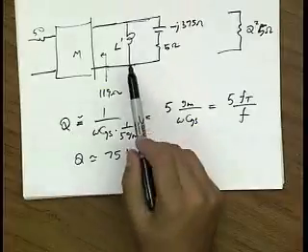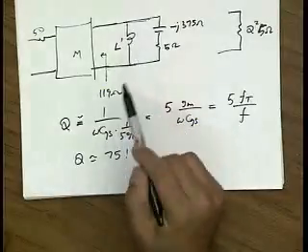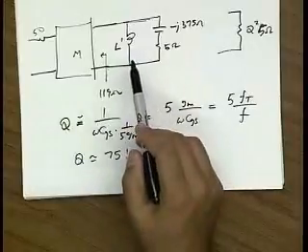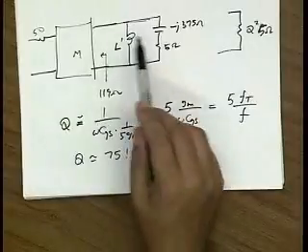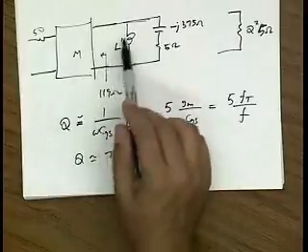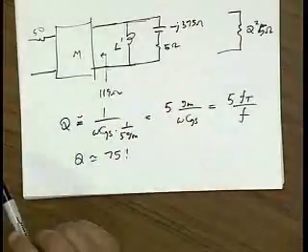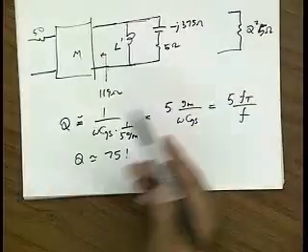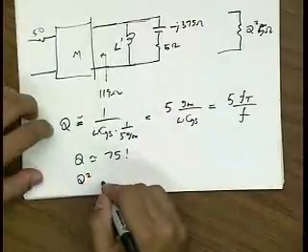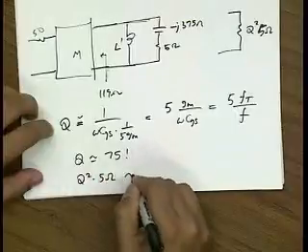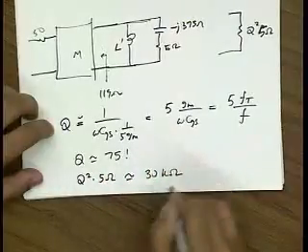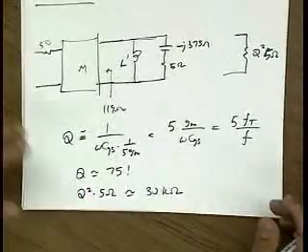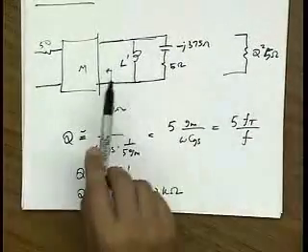First of all, you're not going to be able to find an inductor that has a Q better than 75, even if you go buy the most expensive inductors you can. So really what's going to happen is when you put this inductor down, you're going to add a lot of resistance in parallel, which is just basically increasing your noise figure. But also now notice that Q squared times 5 ohms is something like 30 kilo ohms. So it's in fact not really the right value either. Now it's a very large impedance.